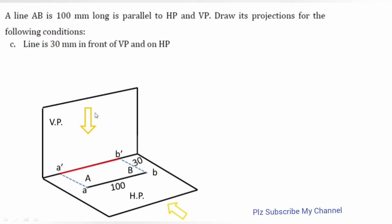This thing, A dash and B dash, which is red in color, is our front view, and when I am observing this line from the top, this line is projected on the HP itself because line is lying on the HP, it cannot go anywhere else. So small ab is the denotation for its top view. So how we are going to draw the final projection, or you can say final solution?